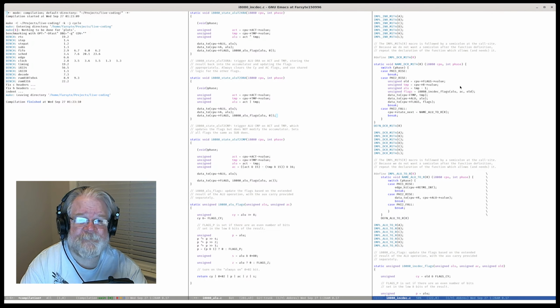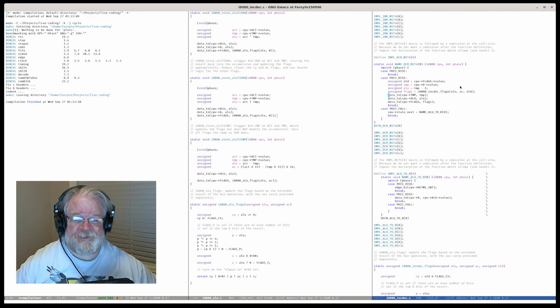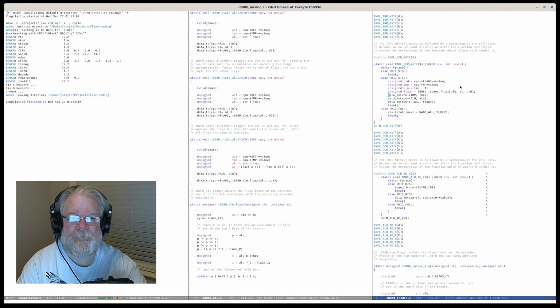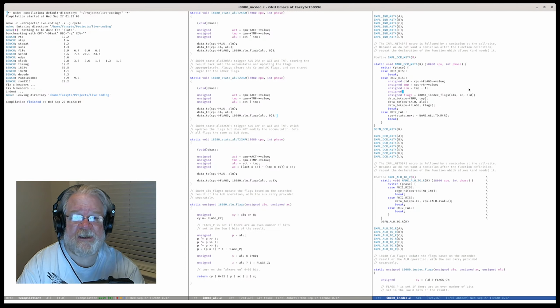What are the chances that the subscriber to temp, well, no, subscriber to temp can't reach back and change temp? That would be a hazard which would halt the system. So this is valid. We compute the ALU. We compute the IncDec flags. Unsigned AC is equal to 16 ampersand ALU ampersand 15 minus 1.